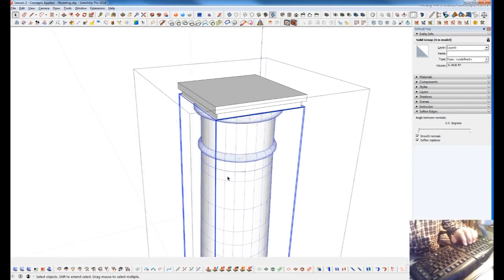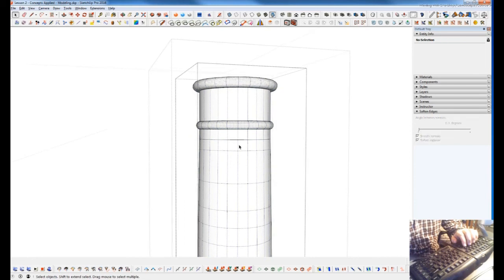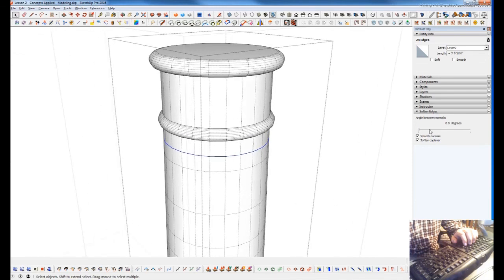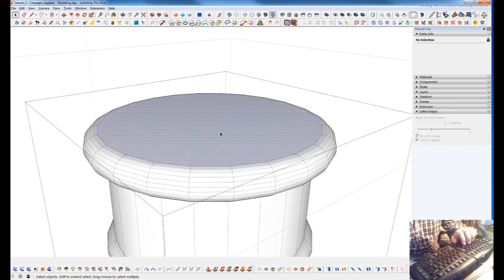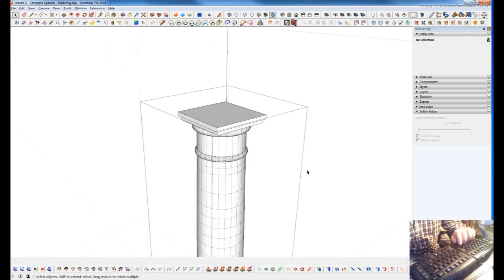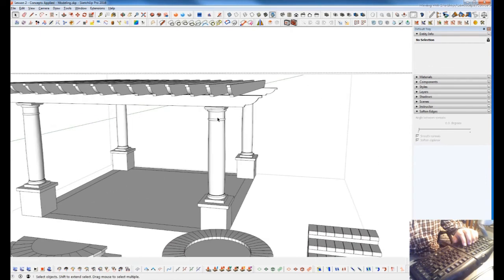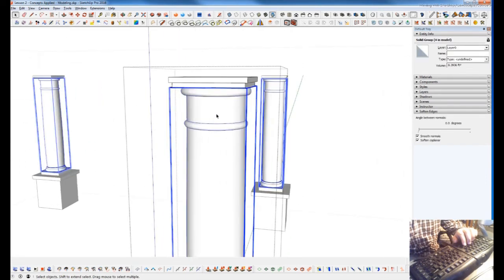So they were kind of doing it all along, but because I export out of SketchUp into another software for my rendering, and because I am so particular with my rendering process and things that I do with rendering, not necessarily with a shape like this, but a lot of times I do displacement and things that really requires good solid clean geometry. So unsoften where it's not necessary, turn off hidden geometry, and now we should have a very nice clean surface.